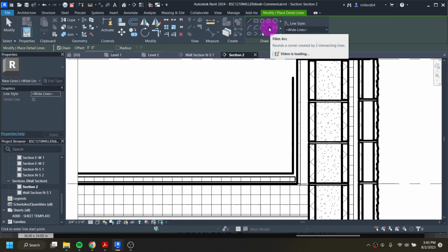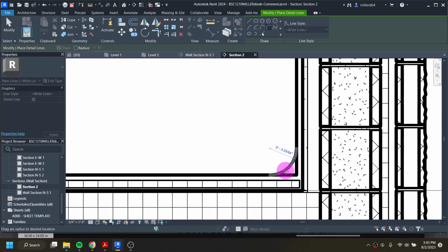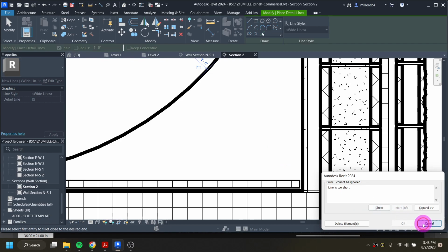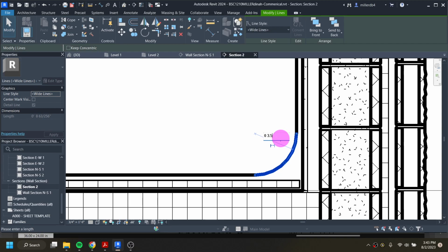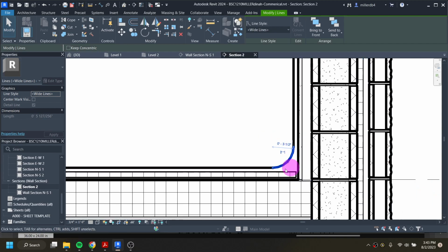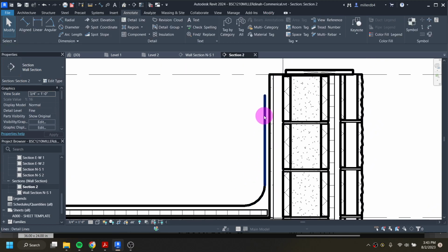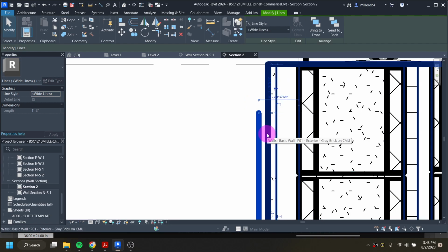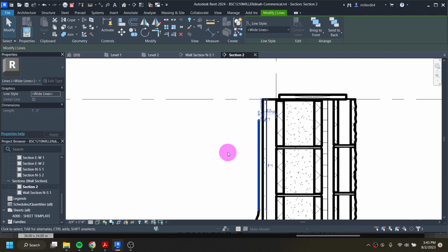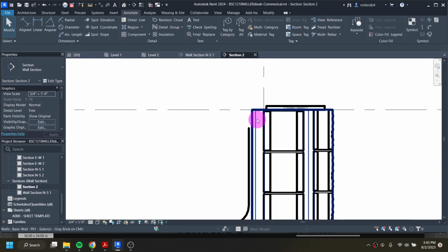And then I'm going to use the Fillet Arc to just make this have a curve. If I wanted to even type in a specific amount, like if I wanted like 3.5, I can place it, and then afterwards I can edit that witness to be, I did 3.5 feet. I do that often within this, at least. And that way I could have a specific arc size if that's something that I needed. If I wanted this to be a specific distance away from something, I can, or I can even just kind of eyeball it into place, which is what I kind of prefer to do.